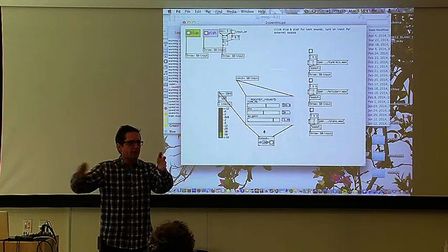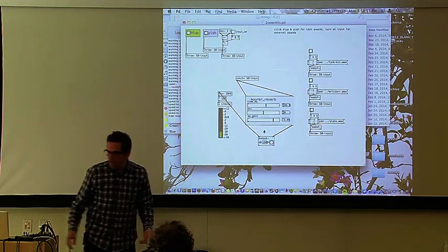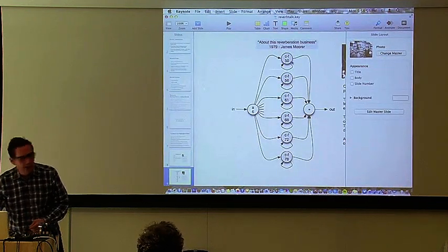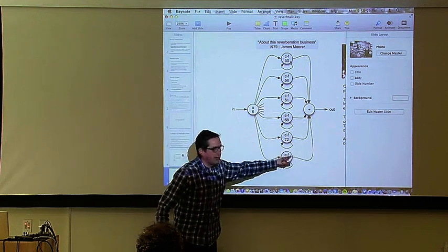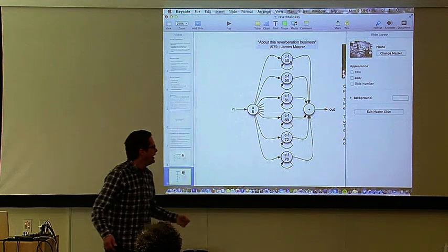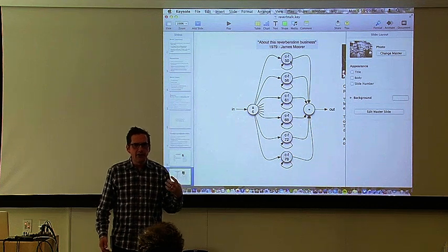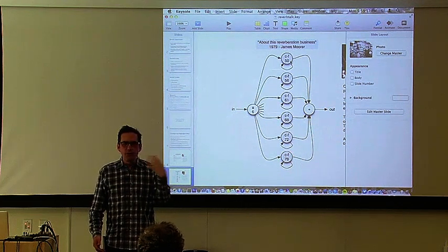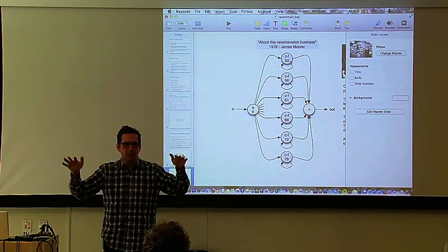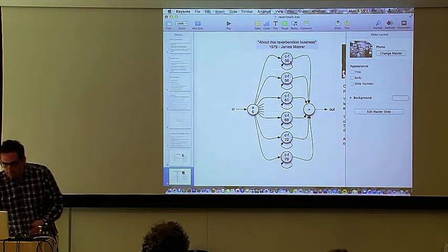Because now you have a progression of darkness. Things get darker as time goes on, because right in the comb filter, right in the echo path, is the filter. So every time you go through the filter, it gets darker, and it acts like a real room that way. It also gives you the ability to have clarity. That is, now the new sound can sit above the reverberated sound, because the reverberated sound has a limited spectrum. We have more spectral roll-off as the reverb proceeds.